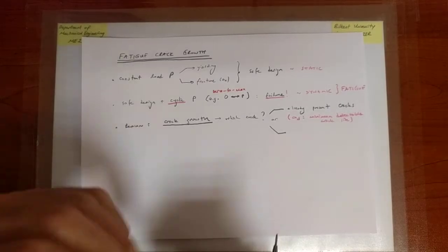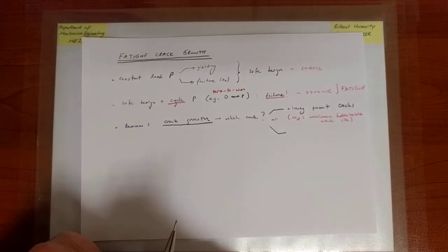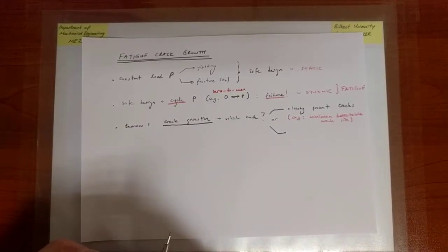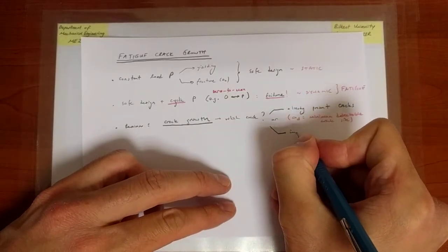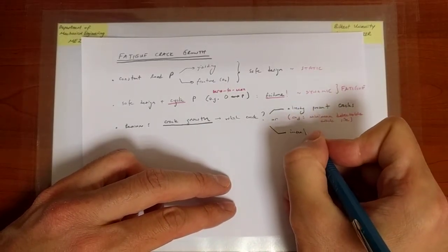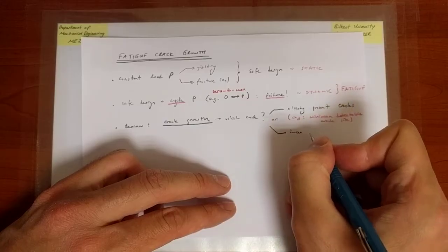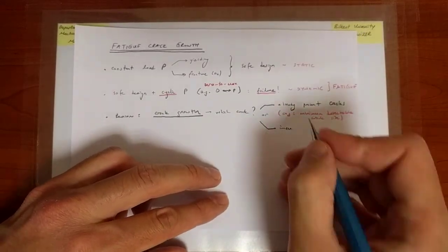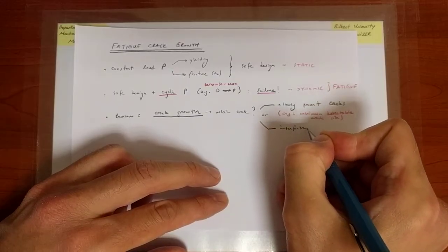That's the way we defined a perfect, ideal crack. Now, however, there may not be a crack. There might be a tiny void in the structure. There might be imperfections. A void would be, let's say, an almost spherical cavity. A spherical cavity is not a crack. The stress concentration is not infinite.